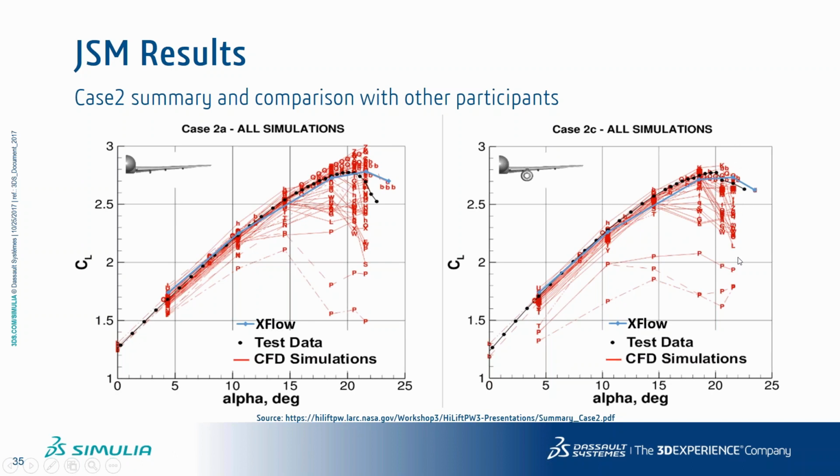It's extremely hard for a steady state code to converge in these conditions, because the unsteadiness of the flow becomes strong. You've got a lot of separation, massive separation, which is hard to predict if you don't use a high fidelity turbulence model, and it's not an easy CFD simulation. It's also a big simulation. You see that the meshes were 50 million or 100 million, or some participants go to 200 million elements. They run on huge clusters and so on. So it's a pretty expensive simulation for most people as well.